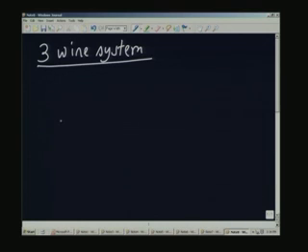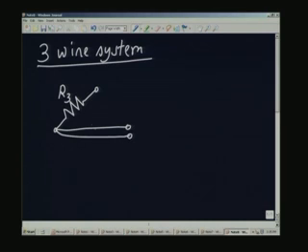So, what I will do is I will draw a simple sketch here. This is the gauge, which I will call as R3. I will always use the symbol R3 for the gauge, and it has 2 leads, and these are the 3 lead wires which are going to come out of that. So, this is R L, this is also R L, this is also R L. These are the 3 lead wires coming out of the 2 ends of the strain gauge.